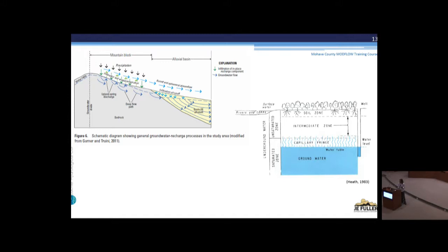There is a hitch here, an important one: there's something between the surface where plants grow and access soil moisture and the groundwater system, and that's a big something called the vadose zone, or the unsaturated zone. As I said earlier, when we talked about how recharge makes it through the unsaturated zone to the water table, that takes a long time because sometimes it has to go through hundreds or even thousands of feet of unsaturated zone before it actually hits the water table. And whatever water is stuck in that unsaturated zone is inaccessible. It's unavailable for human use.